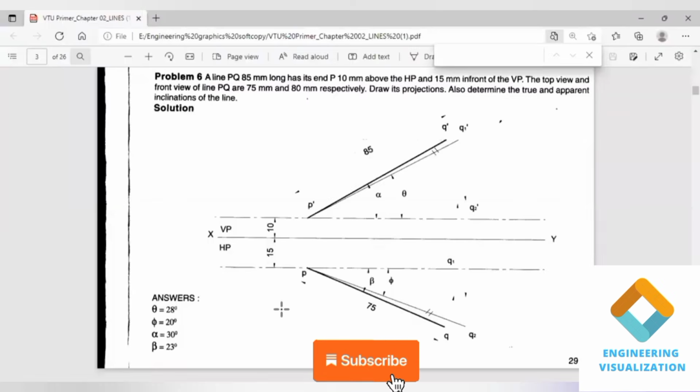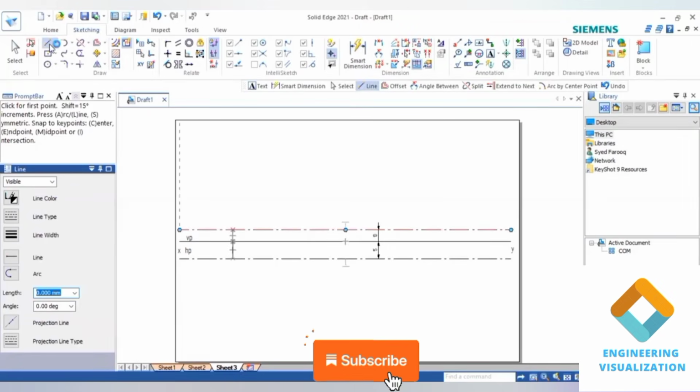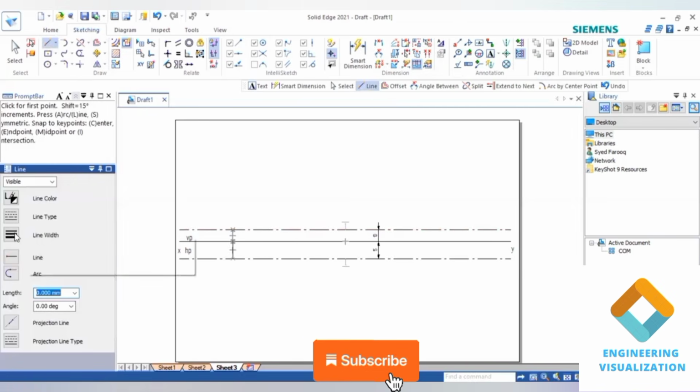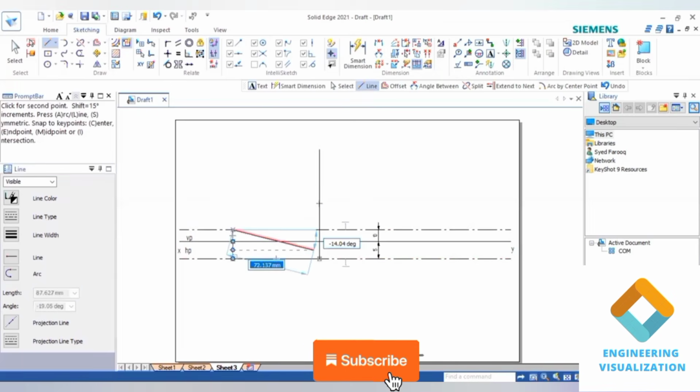Using this 75 and 85 mm, we have to draw the true length. First I'll be taking this apparent length in top view, okay, giving 75. So from this end I'll be drawing a vertical straight line. So from this end I'll be measuring for length of true length we have to give.